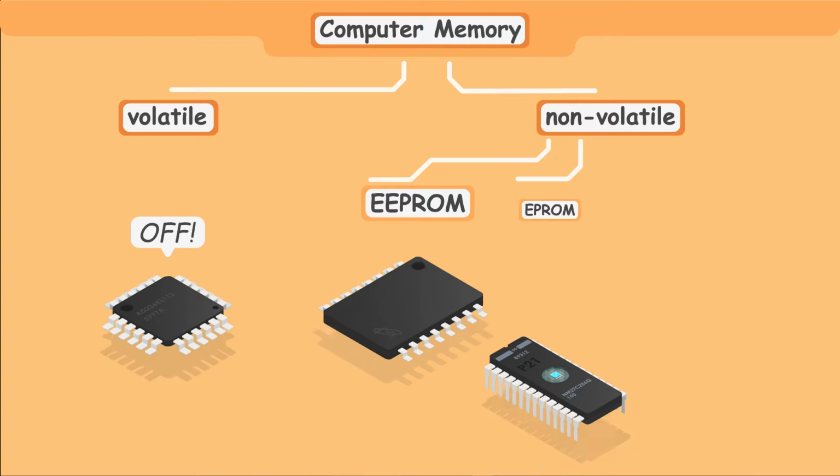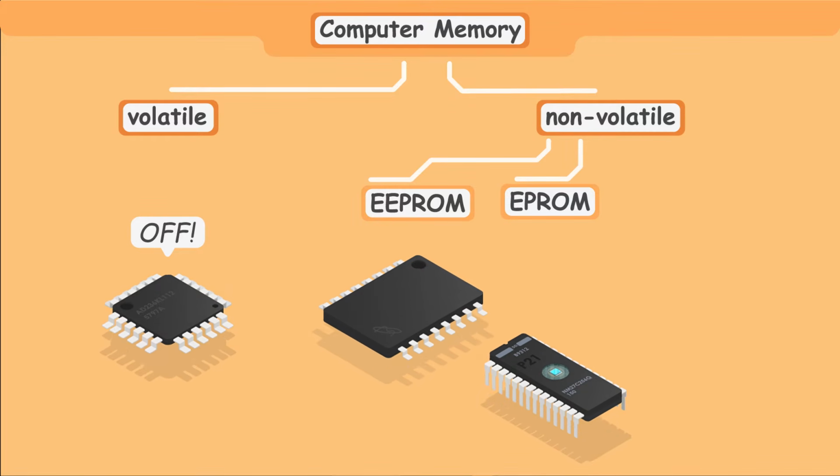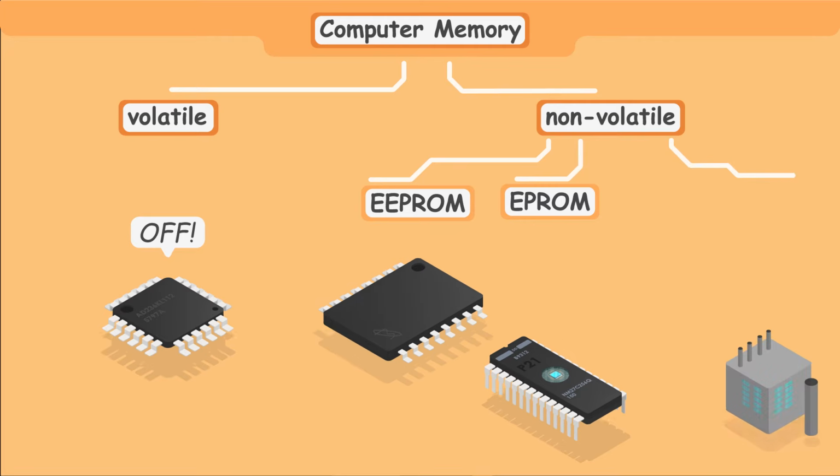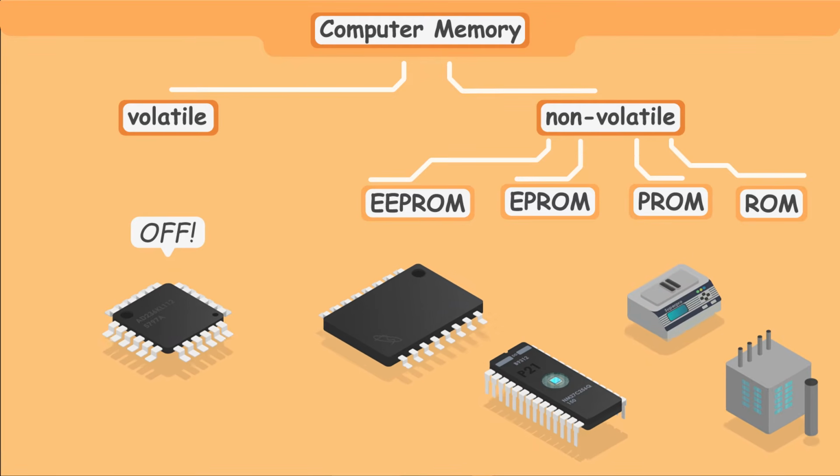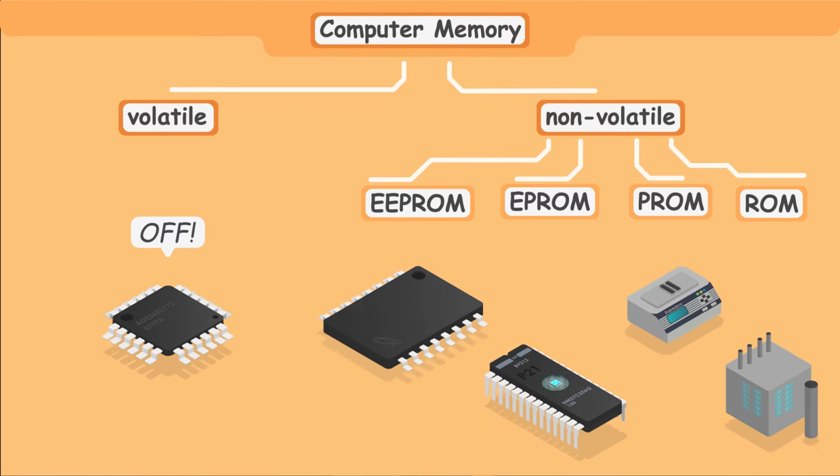For example, EPROMs can be programmed electrically too, but are not electrically erasable. They depend on UV light that must shine through a small window onto the die. In ROMs, data is written into the chip during manufacturing, whereas in PROMs, data can be written into only once and through the help of a special programmer.